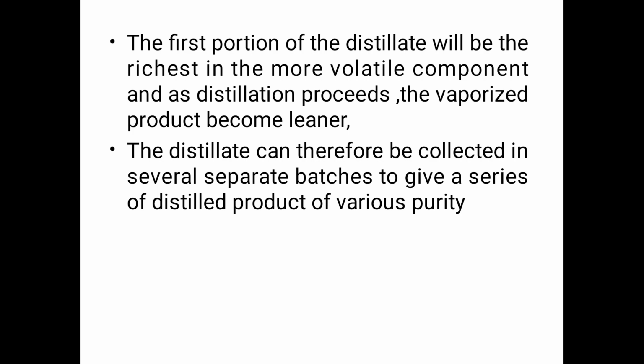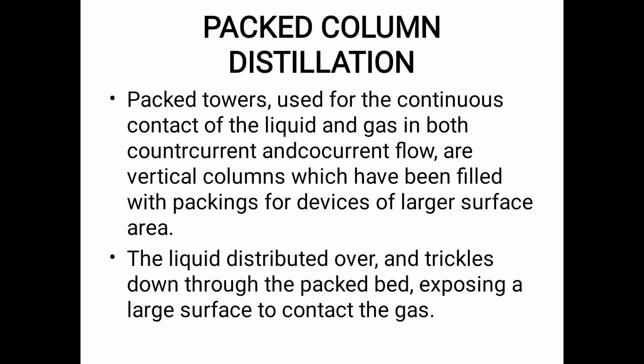And as distillation proceeds, the vaporized product becomes leaner in the more volatile component. It is called distillate. The distillate can therefore be collected in several separate batches to give a series of distillation products of various purity.